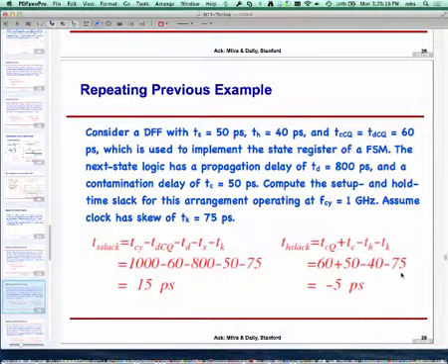For the setup time, there are very fancy circuits. What they do is they put in additional circuits on the chip which monitor to see if errors are happening, and if errors are happening, they tell the clock to slow down. All of that happens automatically, or they tell the software to repeat the instruction. So for setup time, there are all sorts of tricks you can do.